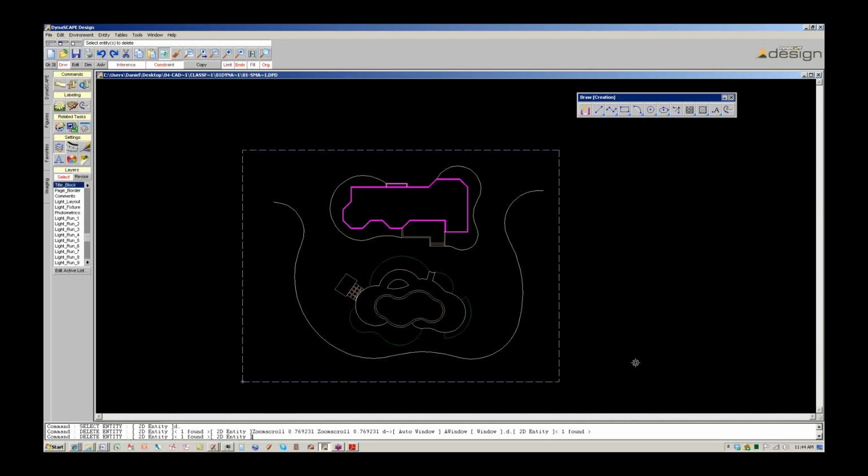Now, I've seen a lot of DynaSCAPE files and site plans. You only put the information on for what you need to create 2D drawings. Either you're going to create an illustrative or you're using it for design build drawings, your as-built drawings or whatever it might be. You're not going to create line work that you don't need, right? What you do need to do before you actually extract and replace and save this file for SketchUp is do 2 things. One, you want to make sure that all your areas are closed.